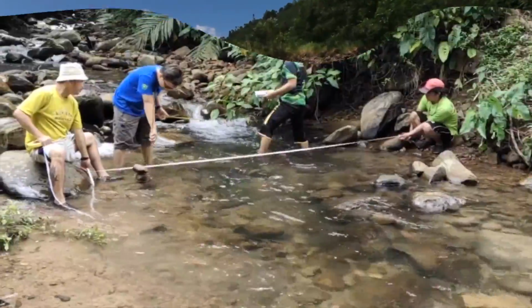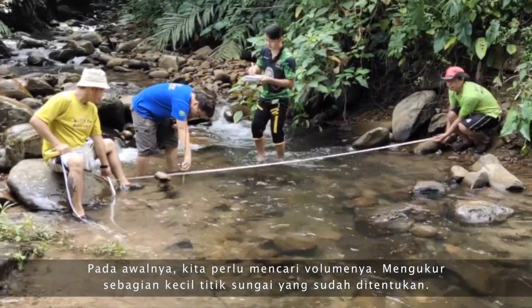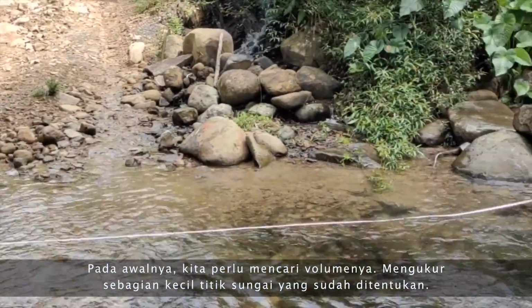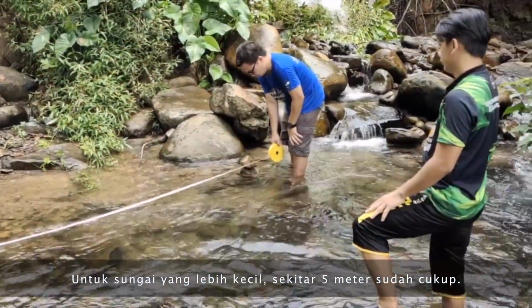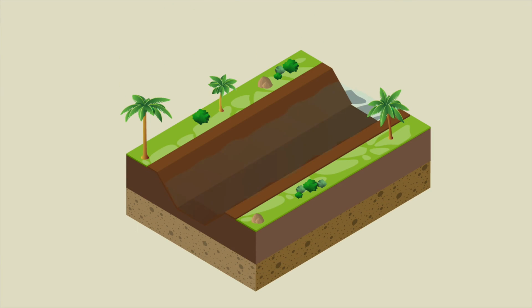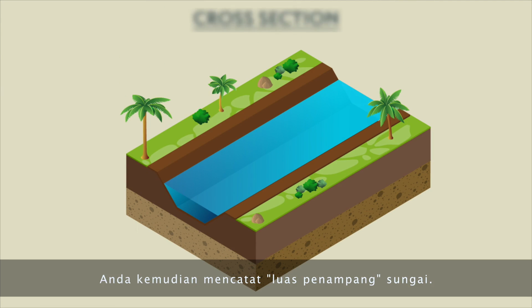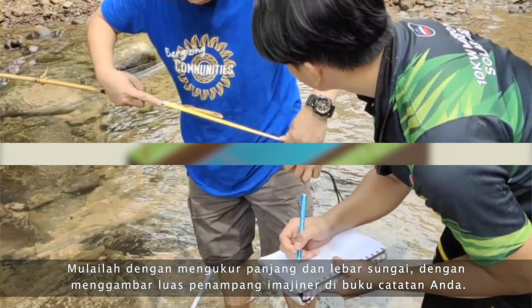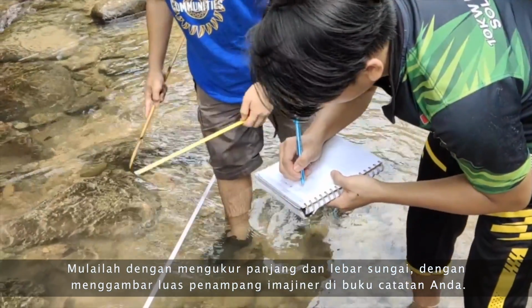Now to the measurements. First, we need to find the volume. We do this by measuring off a small section of the river or stream. For a smaller stream, 5 to 10 meters should be sufficient. You then take note of the cross-sectional area of the river. Start by measuring the length and width of the river, drawing an imaginary cross-section area in your notepad.